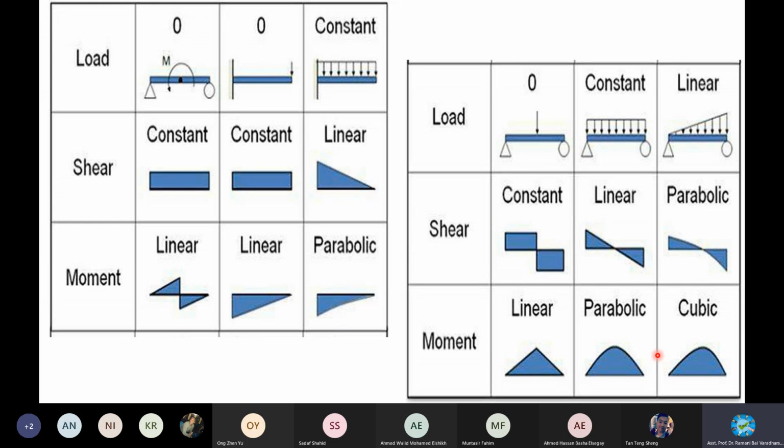Coming to bending moment, I repeat, UDL is parabolic, right? Not an inclined line like point load, parabolic shape. Start from here, free and 0, no distance, free and 0, and then slowly increasing because of the loading. Loading to distance is there, very high distance, big one, and then in the other direction, it's slowly reducing to 0 at the other end. Okay, because the moment is 0 at this point. So it's parabolic. Maximum occurs at the middle.